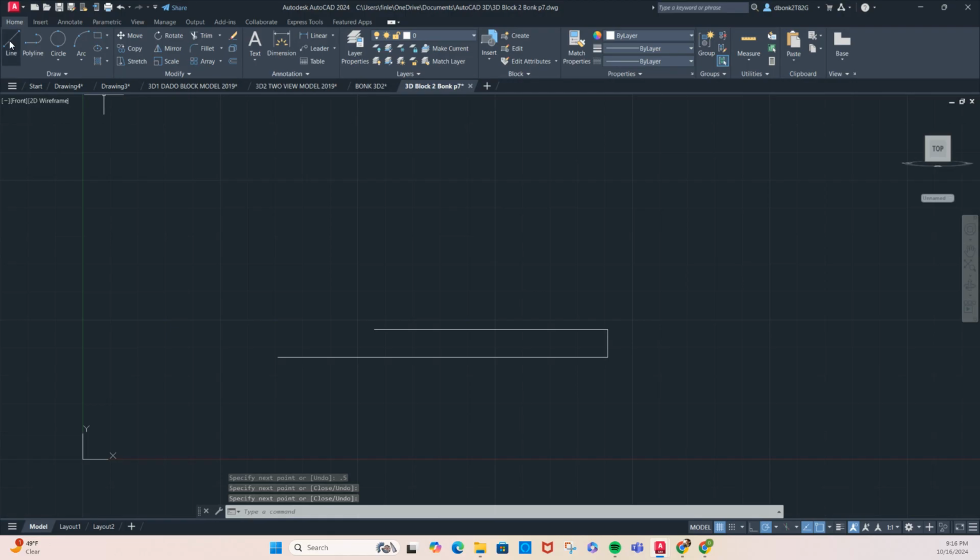Now, back to the line. I'm going to draw the height of the block, which is 1 3/4 inches. That looks like 1, minus symbol, 3/4. Enter. This is going to be done in 3 little segments. You'll see. Hang on one second.